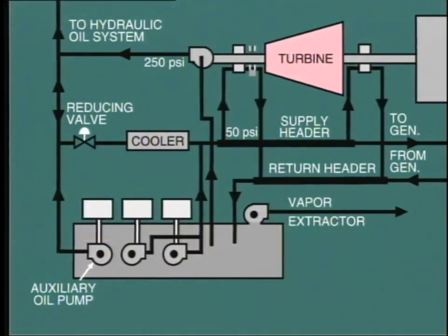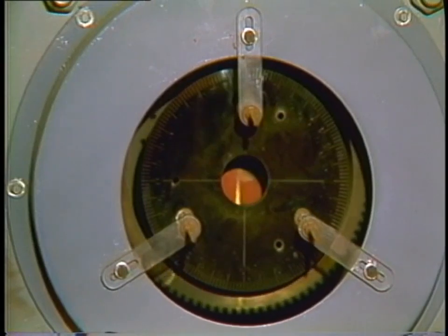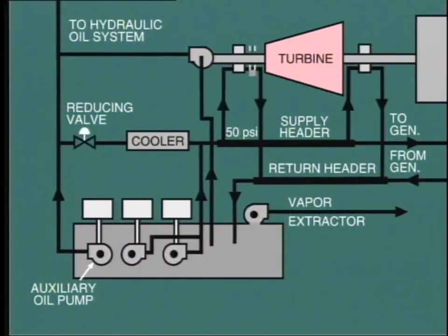When the turbine is out of service and operating on turning gear, we still need to provide lubrication to the bearings. However, in this situation, with hydraulic oil not required, it would be inefficient to run the large auxiliary oil pump. Instead, a small pump is installed known as the turning gear oil pump, and this provides sufficient oil for lubrication only. And as before, there is a DC emergency pump which will provide lubrication in the case that all AC service supply power is lost.